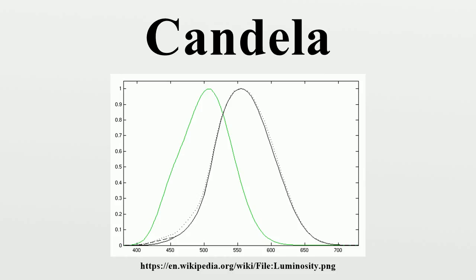Relationships between luminous intensity, luminous flux, and illuminance. If a source emits a known luminous intensity I_V in a well-defined cone, the total luminous flux phi_V in lumens is given by phi_V equals I_V times 2 pi times (1 minus cos A), where A is the radiation angle of the lamp, the full vertex angle of the emission cone. For example, a lamp that emits 590 candelas with a radiation angle of 40 degrees emits about 224 lumens. See the table for emission angles of some common lamps.